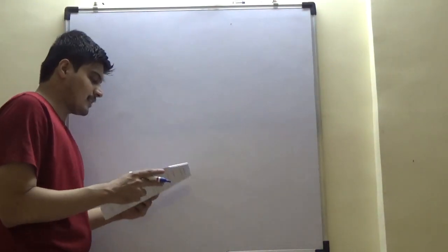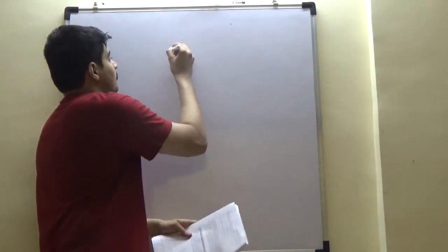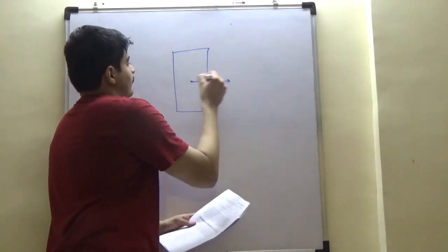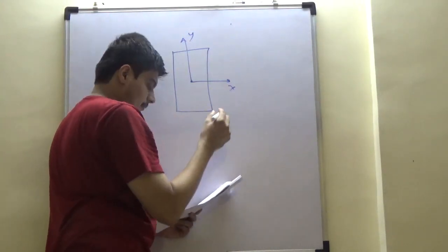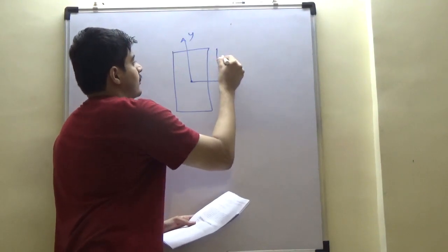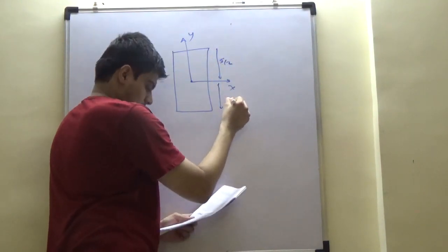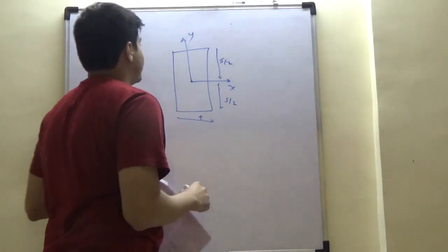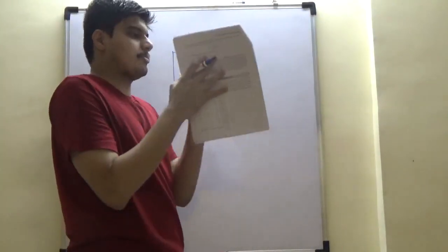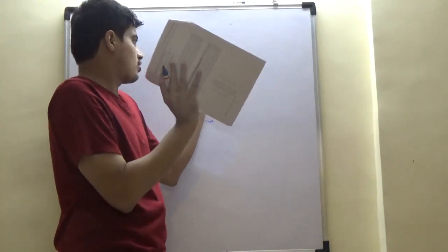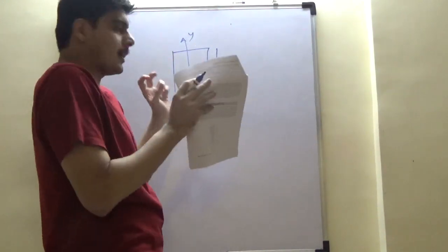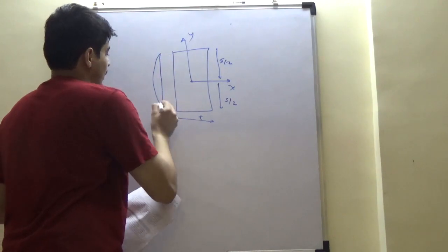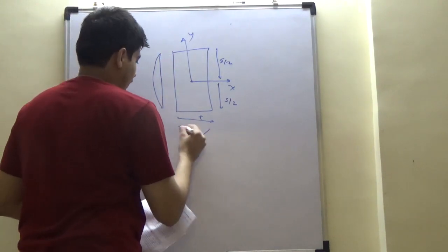The third section, therefore, as we said, is now of thin rectangular plates. They have this length, which is S by 2, S by 2, thickness is T. Right? Now, imagine this to be a cross section. There is going to be this twist, and then there is going to be warping, which is going to come out.